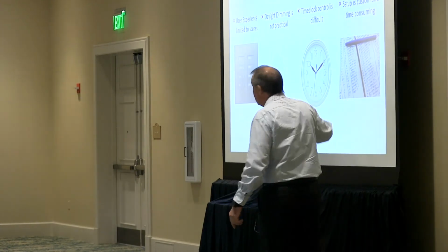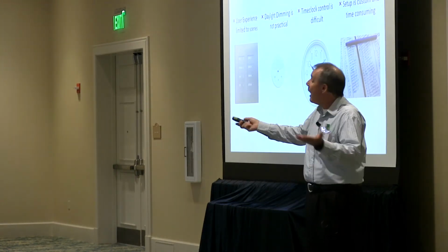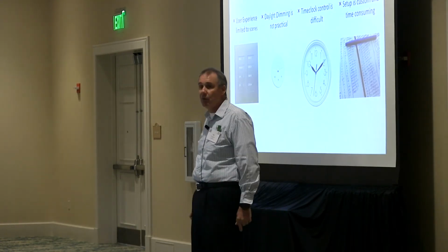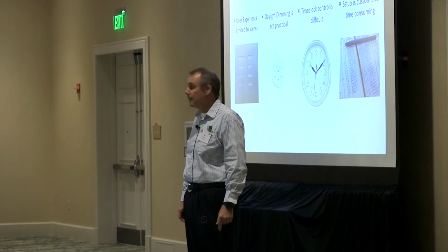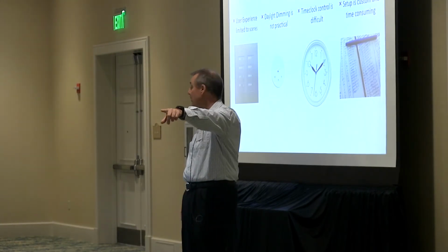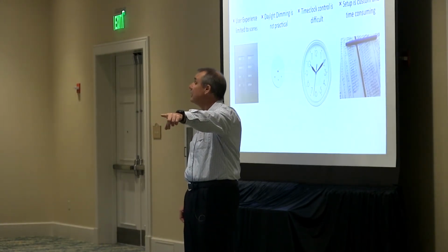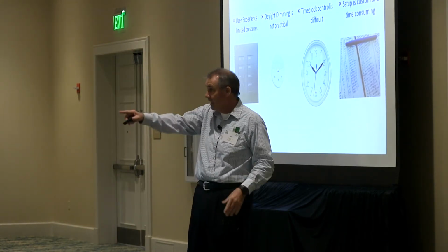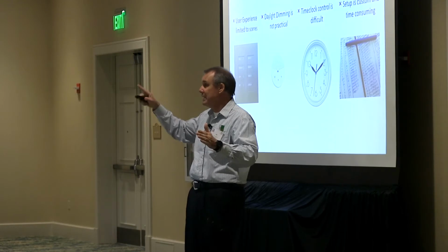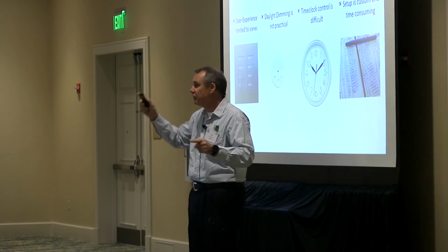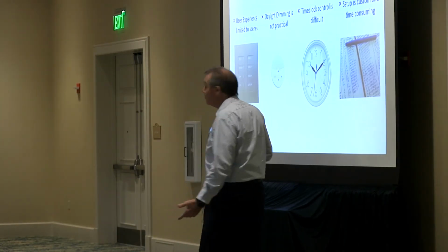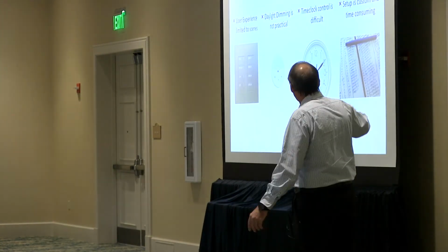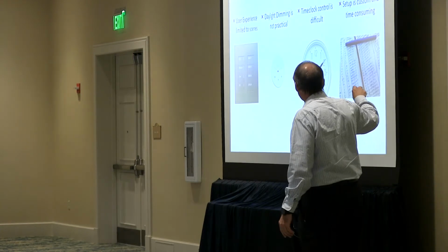You won't be able to do daylight control. Like, how would daylight control work with a tunable light fixture? What would you control? You could do his scenario. You could use the daylight sensor to control the color temperature, and then we'd match exactly, and we would do completely dynamic lighting. There would be no steps in that scenario, or we could change the intensity, or both. You can't do it with what I just showed you.